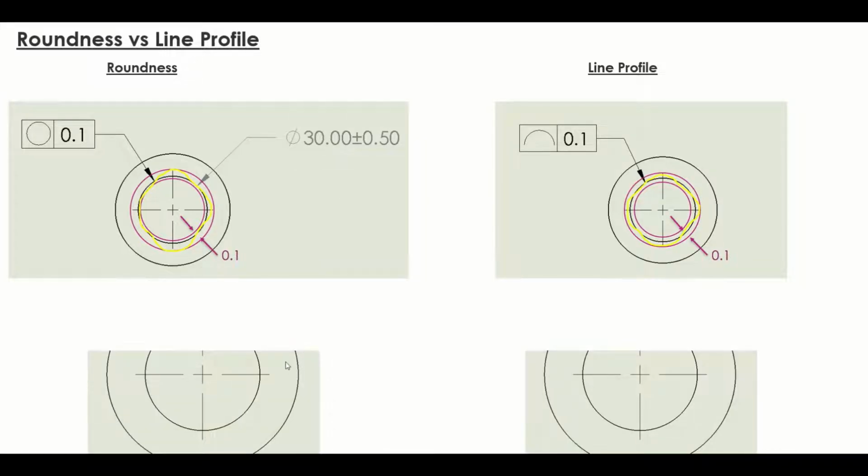Looking closer at the tolerance zone, it is constructed by two concentric circles. Thus, the two concentric circles do not have to be equidistant from the exact circle. In fact, the outer circle is further away from the exact circle compared to the inner circle. As long as all the innermost and outermost points of the yellow curve fall within the tolerance zone, it can fulfill the tolerance requirements. Now let's only focus on the variations of the circles. It doesn't really care about the diameter.